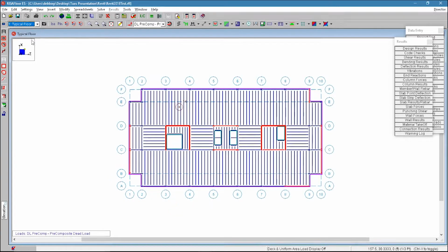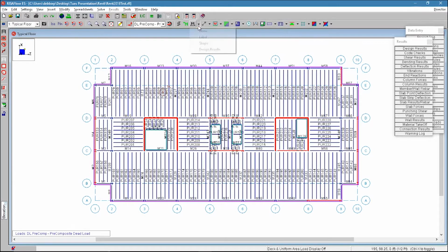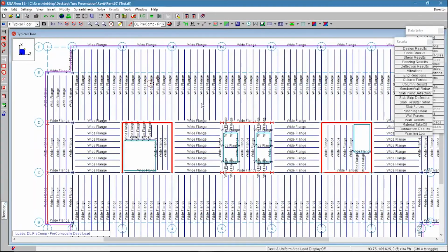So if we jump into our beam supported floor, first thing you notice is that the red indicates a lateral element, the blue is a gravity element. We lay out the floor system on a grid. That's a typical way you might build a model using a project grid. And under that project grid, if we look at the labels here, these members are just going to be shapes, for example, wide flange.